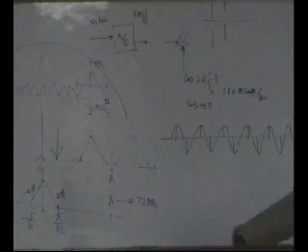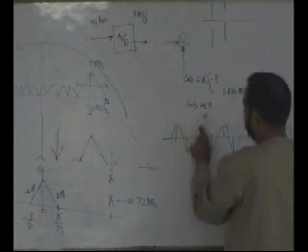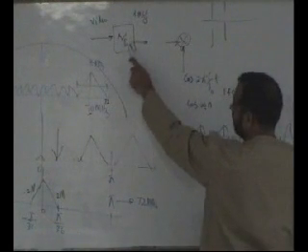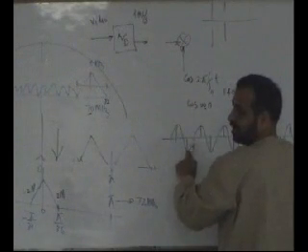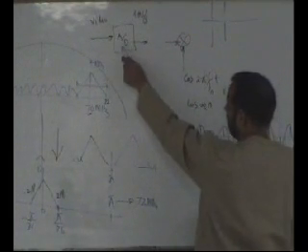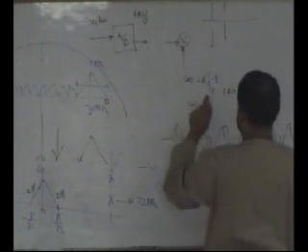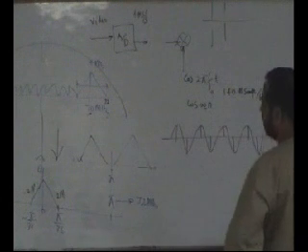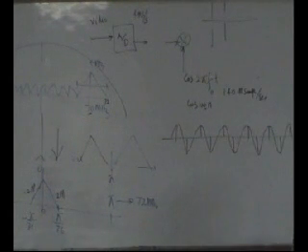So the only way for you to multiply this signal with this signal, if it is done digitally, is that both the sampling rates must be the same. Okay, both the sampling rates must be the same. If you intend to mix 4 mega samples with 140 mega samples, okay, you really need to bring it up to 140 mega samples.